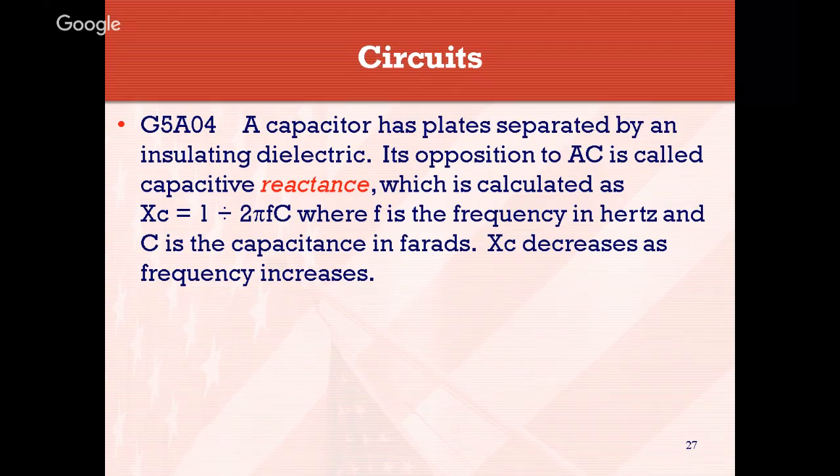Again, where F is the frequency in hertz, remember that, in hertz, and C is the capacitance in farads. So if you're working this formula with kilohertz or megahertz, you want to convert that to hertz.